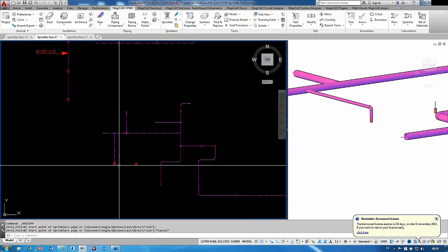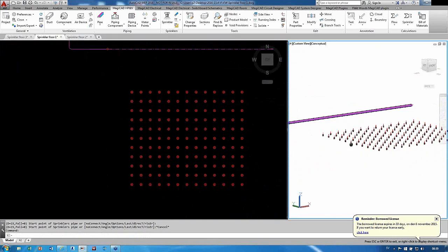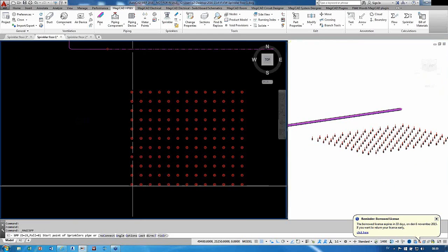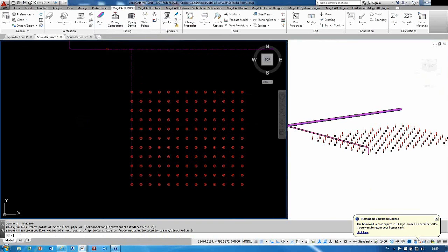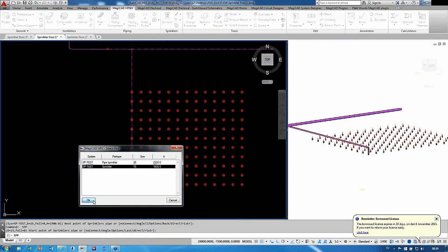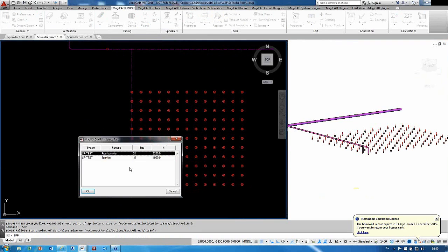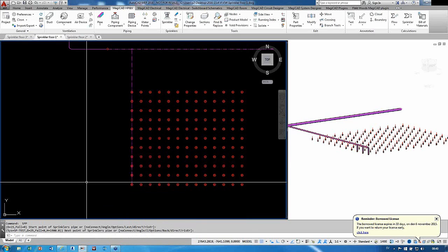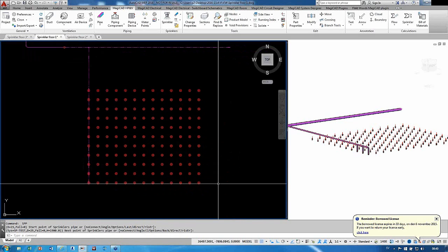So just pointing to the sprinkler head, but of course down over here it can be rather many sprinklers. Yeah, of course we can start to draw from a sprinkler head. I draw it from this point over here. Okay, and then we go with the command again. Now I just took the spacebar, and I want to start from the sprinkler, and I connect to the pipe. And then we continue, spacebar, sprinkler to pipe. But this is, of course, not hard, but it takes time to do it.